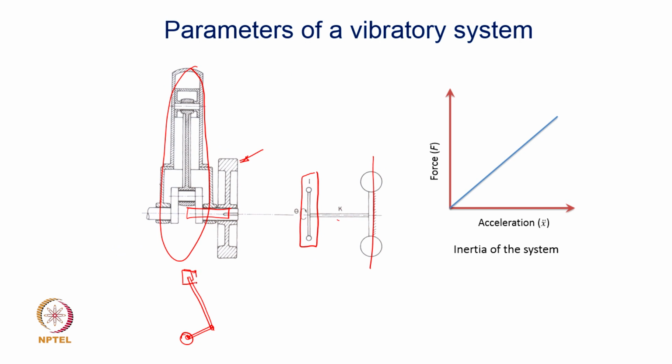So, the way to find out the inertia is to find out the kinetic energy of individual elements and find out an equivalent inertia. And we all know that the velocity of this piston and the velocity of this connecting rod at these positions are going to be changing each instant of time. So, the kinetic energy also fluctuates, and so the equivalent inertia that you can find will also change with time, and therefore, you cannot have a direct linear relationship between the inertia force and the acceleration.